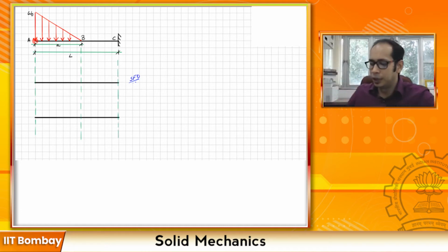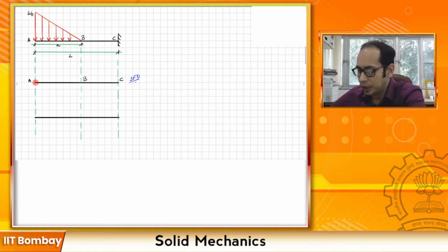All right, so now that we have the guidelines, for the first beam, let's mark the points as well. So this is my A, here is my B, and here is my C. Now, as we hypothesized, at this particular point, my shear force will be 0. So at this particular point, I will have no shear. Now, let's see how the shear force diagram varies.